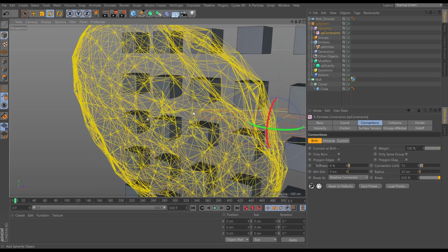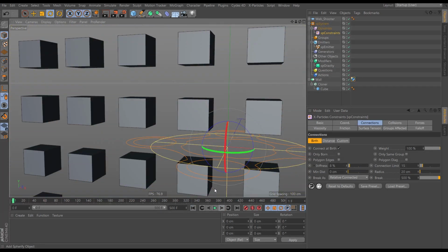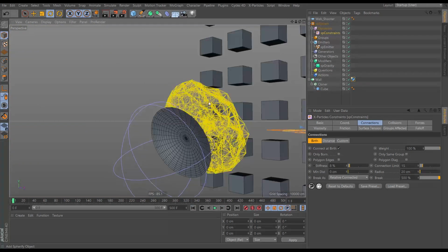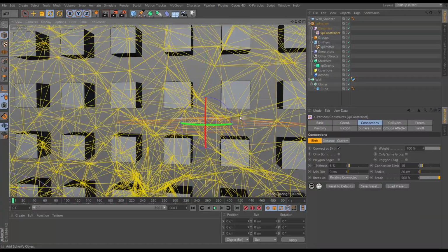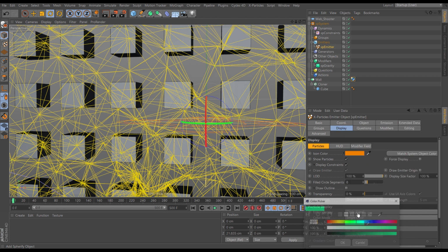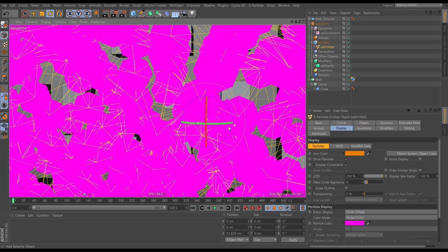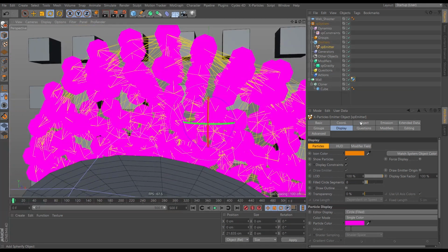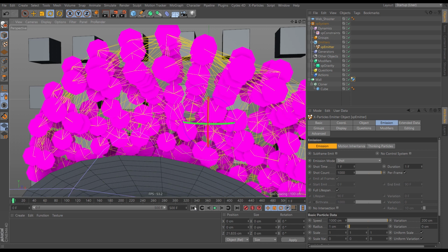I'm just going to dolly in. So relative connected means this. When the particles are born, it judges the distance between them. So let's just take this particle. I'm just going to change the colour of my particles so we can see this a little bit better. I'm going to change the squares to circles filled, and I'm going to make them bright pink. Okay, go back to the beginning. Right. Ha! Too big. Let's put that down to 1 centimetre. And I'll put my ambient occlusion on in the viewport and go again.